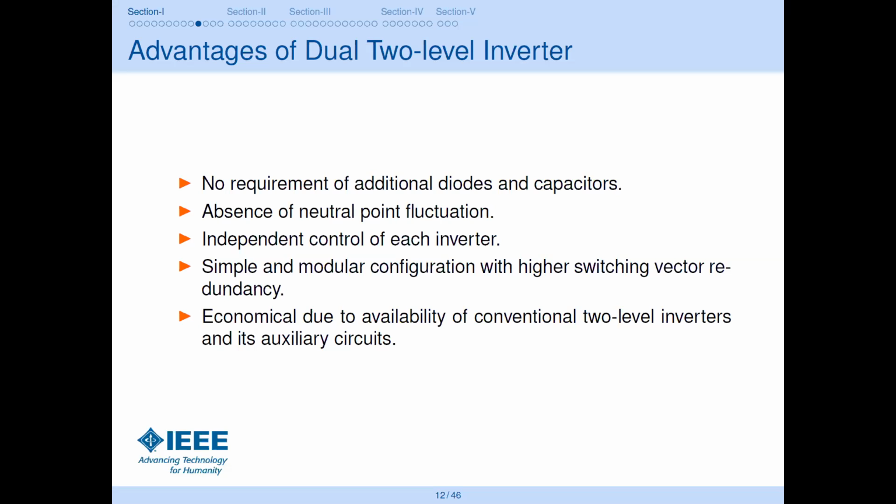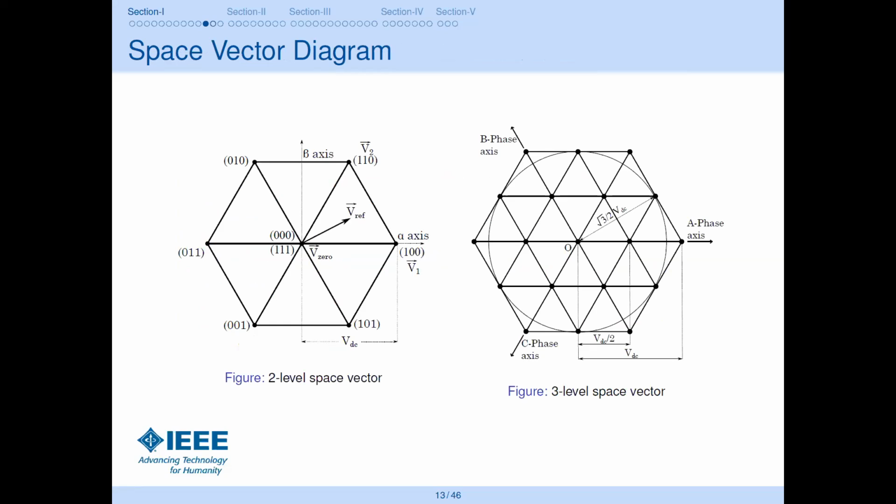So 2-level inverters are already available. The thing you have to modify is on the load side, which is the motor. You have to get an open-ended configuration. So this was the thing I was talking about.